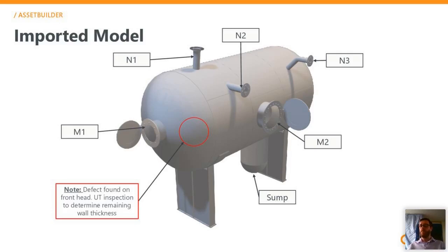So in a matter of moments, you can get a drawing, build a vessel, export it out. You can do pre-operational planning if you use robotic software, or you can use your Word, PowerPoint, and Excel documents in order to interact with the model, mark it up, and then send it out to the field. And if you have crews out in the field, they can pull the model out of the database by exporting it, add to the model, for example, if there's some things missing. So as we know, drawings sometimes are different, and then re-import that back into the database, and then you have a collection of your models.